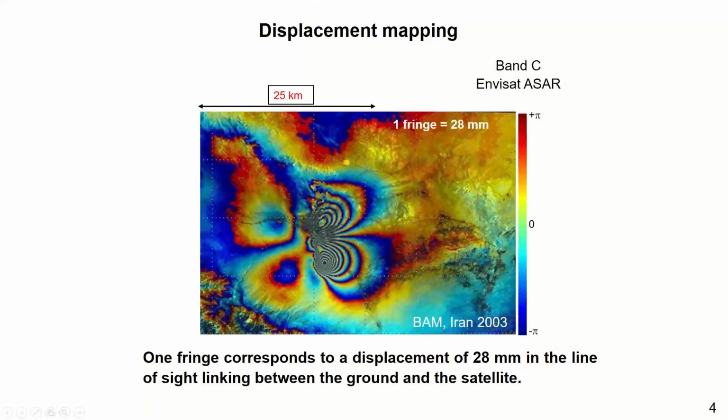So now we try to quantify what exactly is inside this interferogram. The earthquake basically happened in the center of the city, in this area here. So we know that the center part will be affected the most. So now we try to quantify the magnitude of the deformation caused by the earthquake, and we assume that from here to about 10 kilometers far away, the effect of the earthquake will be minimal. It means that the surface is stable or unchanged in the area of yellow color code here.